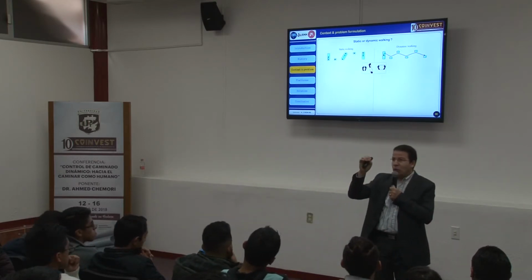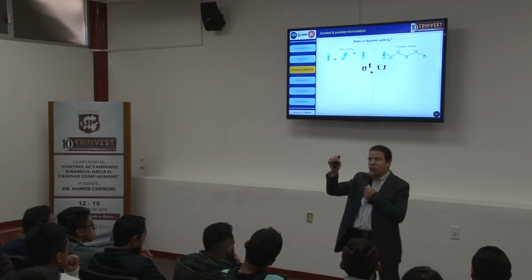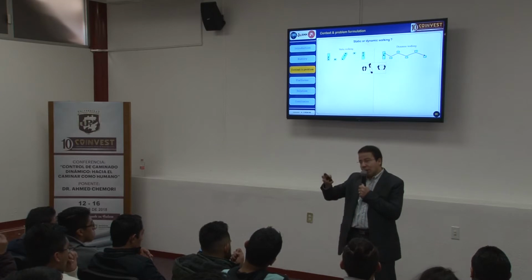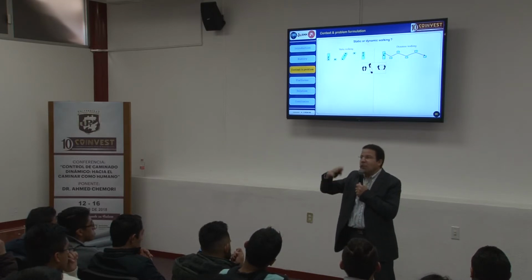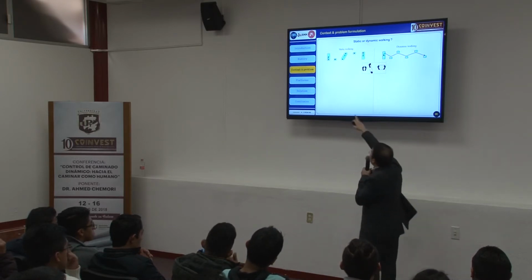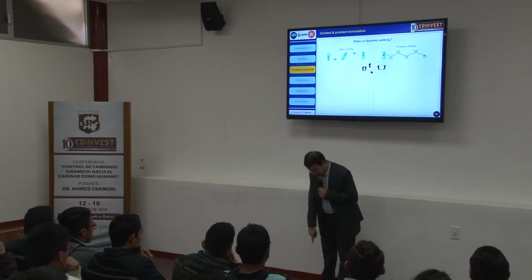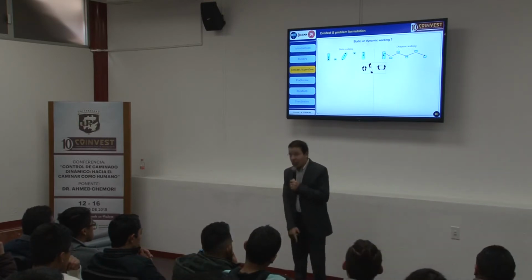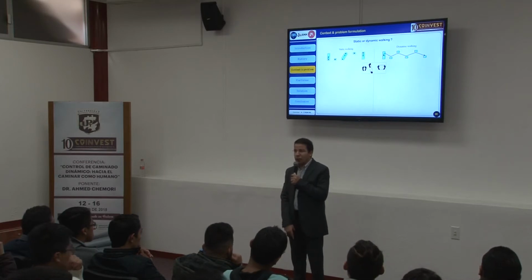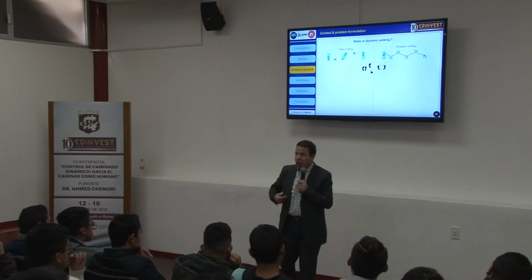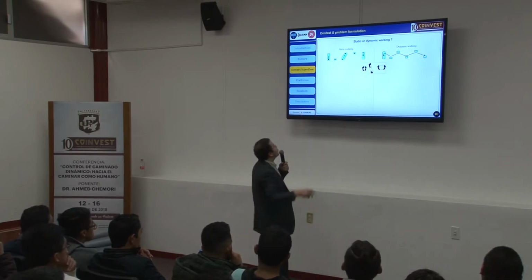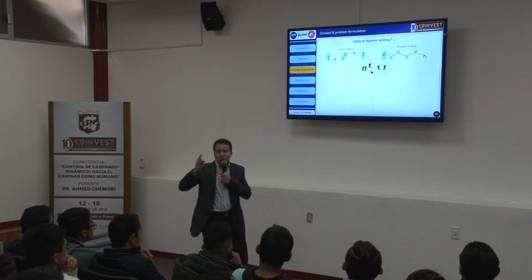You have to keep all the time the projection of the center of mass inside the polygon of support. What is the polygon of support? If you have here two legs, you have just to construct the area including the two feet, and this is the polygon of support. So when you walk, you have to keep all the time the projection of the center of mass, which you can see here as the black square, inside.